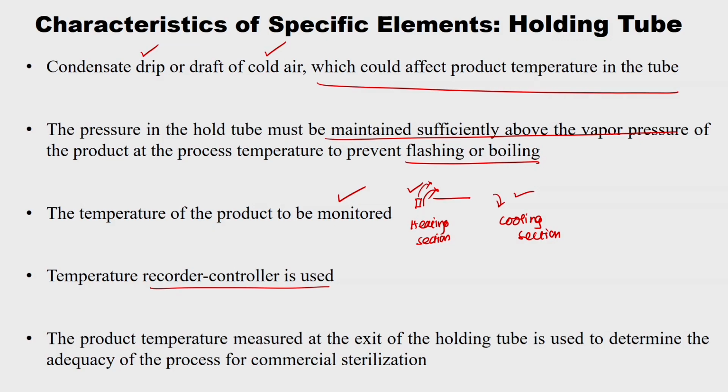The product temperature measured at the exit of the holding tube is used to determine the adequacy of the process for commercial sterilization, measured at the end of the holding tube, right.